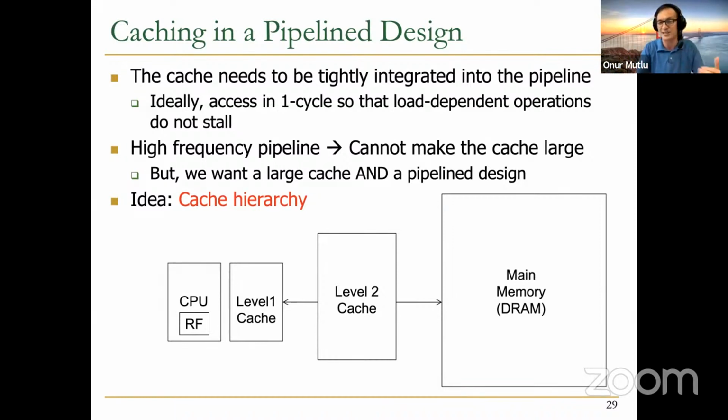And we discussed a lot of latency tolerance mechanisms so far. So if it's 100 cycles, that's bad, basically. That's why we have a cache hierarchy today. Level 1 cache design decisions are mainly dictated by this. Level 2 cache design decisions are much more free, if you will. And level 3 cache is clearly even more free, because they're not tightly integrated into the pipeline.